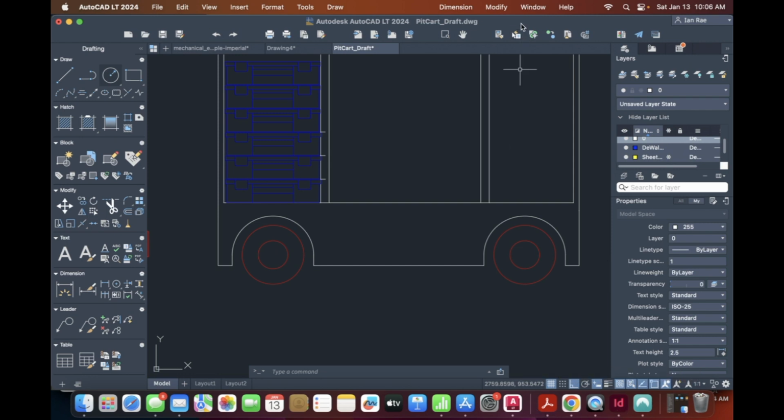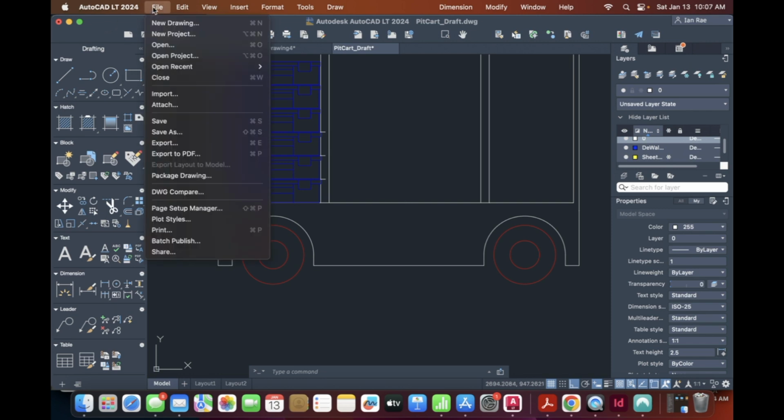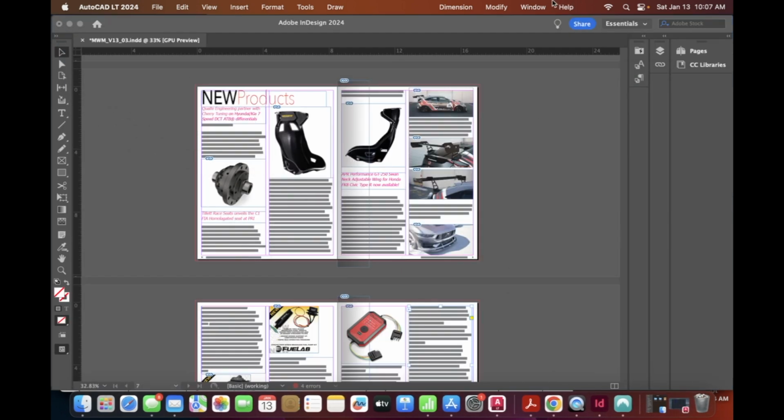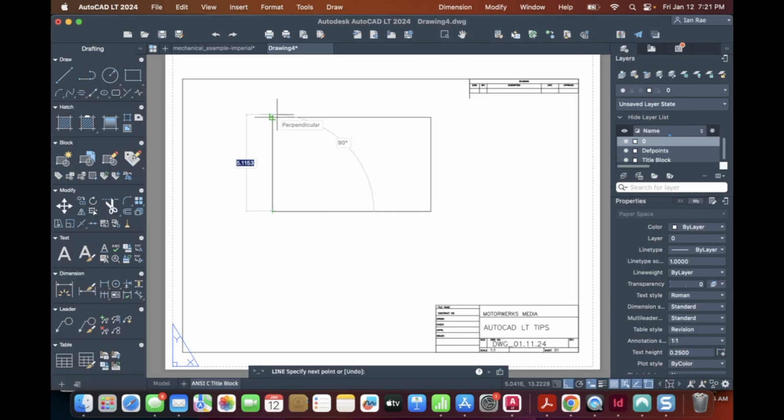The thing about it is that everything is on the screen, allowing you to see where you want to go. So let's go and undo that. And we have up here, if you follow my cursor, an undo line. Again, you can click here, or you can press enter to select it. Go to there, go up, see the perpendicular, click that, hit escape to stop it going anywhere else.